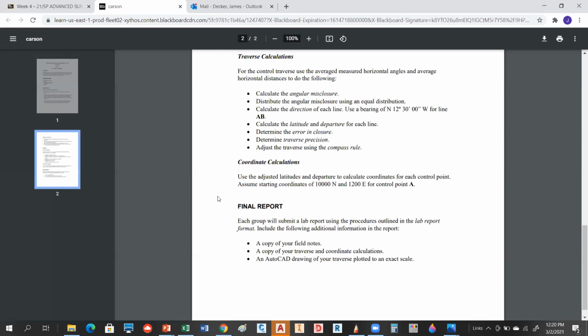We don't know that it is. Those things go out of adjustment. So if those haven't been adjusted in a while, which I don't think they have been, you've got two sources of error. The prism pole may not be adjusted properly, and also you've got a human holding it, which is moving it back and forth. So that's a potential source of error right there as well.